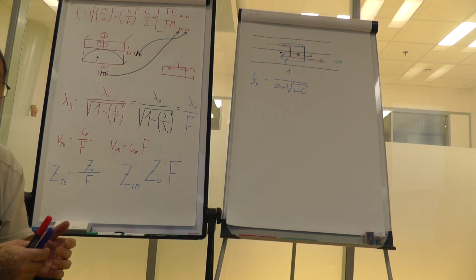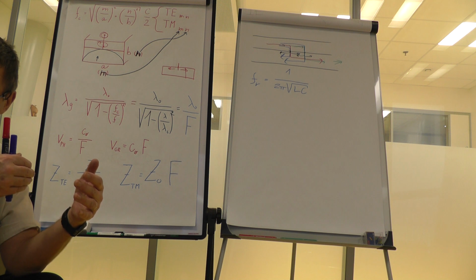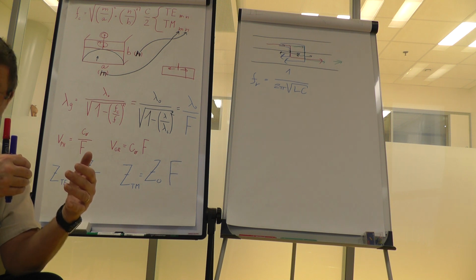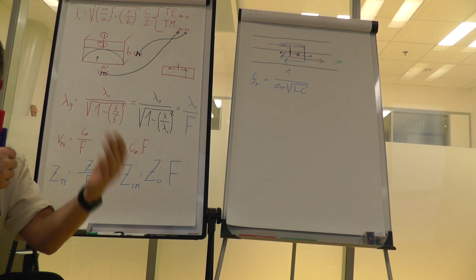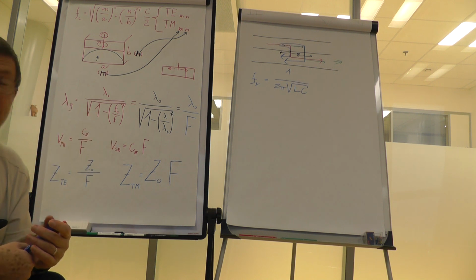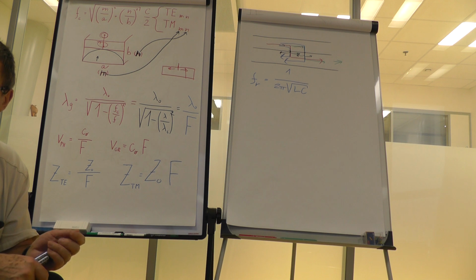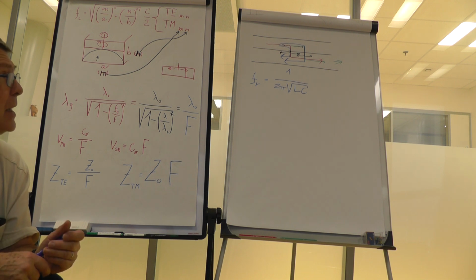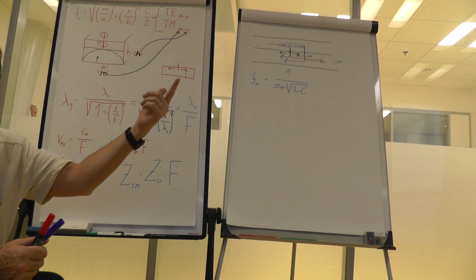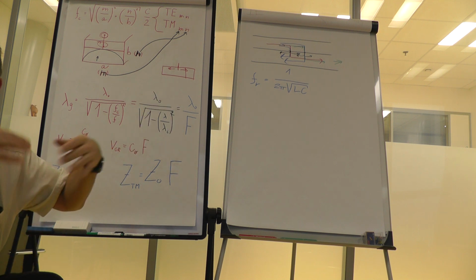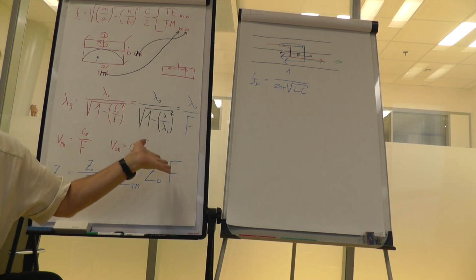Moreover, if you have a strong coil with a very big number of turns and the coil is closed, then you have big inductance and most of the field stays inside, which results in a good quality factor. Now, if you just have a low inductor, let's say 1 turn in the air, then the field could diminish anywhere.